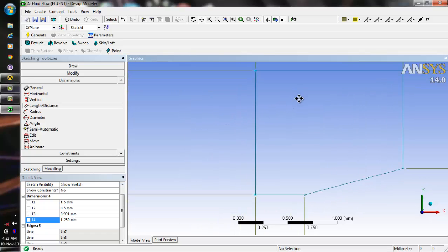So I've already made the geometry. I've already calculated the geometry for the wedge angle of 15 degrees, and how long this length has to be. It is parabolic; we will be solving a parabolic equation. The nature of the parabolic equation is such that if any disturbance is at this point, it won't affect the point before it. It will affect the point after it. So you don't need much of it in the domain. This slant body acts as your wedge.